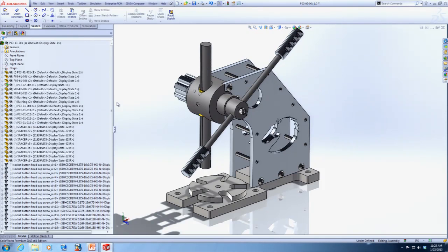Sure. Yes. You may not want to address this, and I would understand. Sometimes Toolbox can be a real problem. I know that when our company switched over to Products, Toolbox was kind of crazy for about a year and a half. So strategically, are there advantages to taking fasteners, washers, things like that, and not using the parts out of SolidWorks Toolbox? Rather, just make a discrete part, maybe make a family table or a design table. Here's 4 parts, and they're not going to get messed up as they get transferred back and forth to PDM Works or Enterprise.